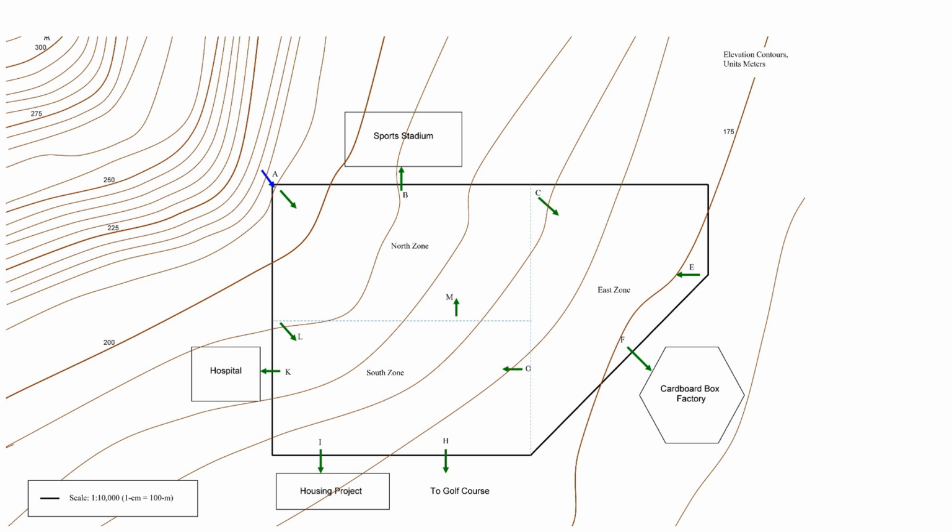And you're going to go through an optimization process of making one pipe a little bit smaller and seeing if it gives you adequate pressure at that location within a range of allowed bounds. You'll go through and figure out where on this hillside you should locate a reservoir to cause pressurization in the network, and then you're going to go through the juggling process of, if I tell you how much the pipes cost, is it worthwhile to spend a little bit more to take the reservoir up on the hill, because that's going to increase the pipe length, but then the higher the reservoir is on the hill, the bigger the pressure is in the pipe network, and that would allow you to make smaller pipes throughout the pipe network.